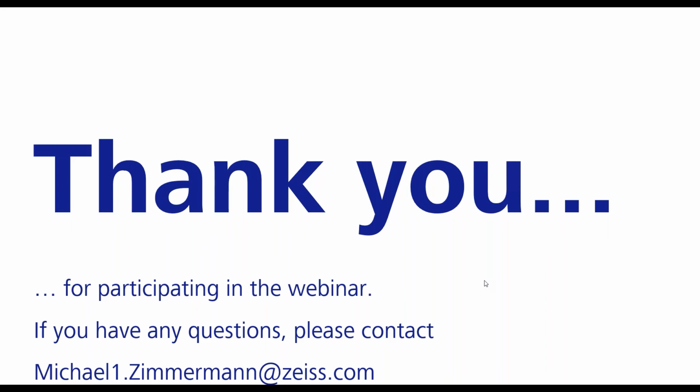All right, I see the first question. It is, do reflective surfaces bother the dot scan? Good question. For this, I have to explain the technology a little bit. The dot scan is a white light sensor using the chromatic confocal principle. The advantage of this principle is that mirroring surfaces, as for example the knee, are no problem to measure.